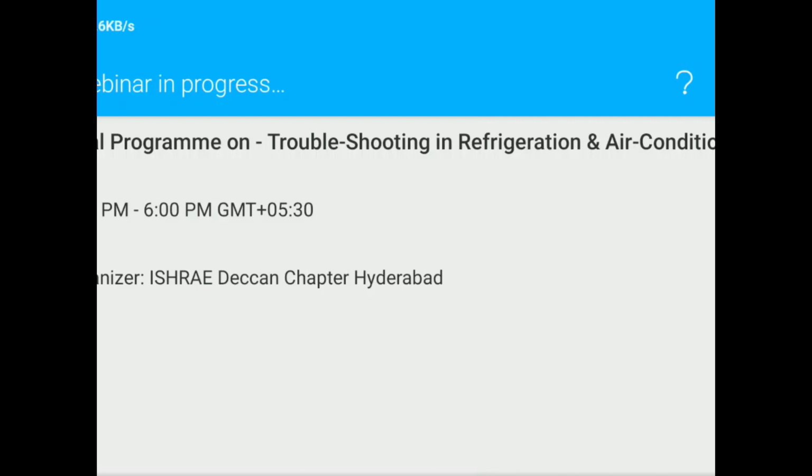So, your second question, about the economizer. Generally, we use an economizer for improving the cycle efficiency. Unless you have a liquid suction heat exchanger here, it may improve only a little. But in modern economizers, we use the economizer in the liquid line. We take some portion of liquid and cool the remaining liquid so that I can improve the cycle efficiency. That is where the current economizers are used.